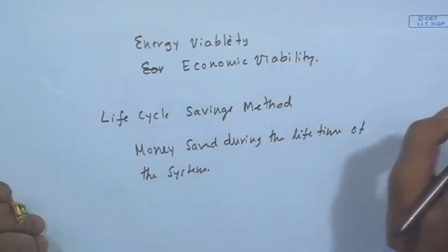If you put down all the income, mainly due to the saving of the energy, tax benefits and government incentives, and the expenditure, which could be the repayment of the investment plus the inflation plus the interest rate on the bank and some maintenance plus auxiliary power, all these come under expenses. So, that is converted into today's monetary value, which is called the present worth factor in economic terminology,